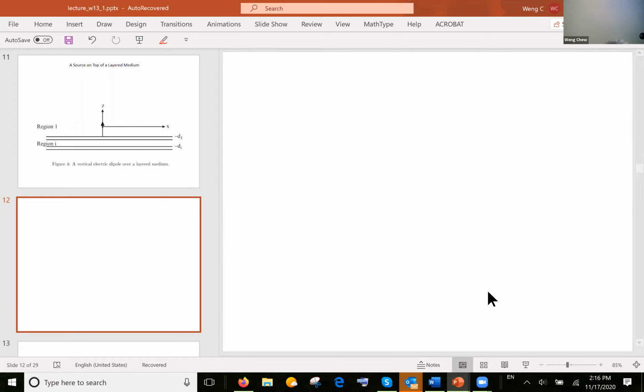Maybe I make the problem simpler. For the single interface problem, if we have an electromagnetic wave incident on a single interface, how must we decompose this plane wave into what kind of two plane waves in order to solve this reflection problem? Do you remember what we had to do? TM mode components. Very good. Excellent. We have to break this into TE and TM polarization.